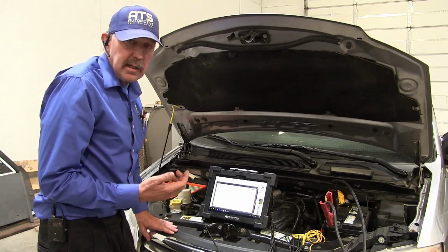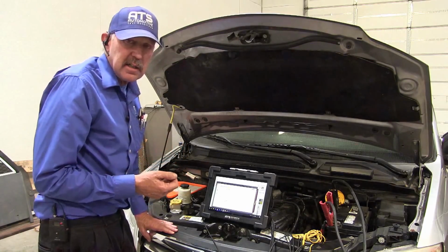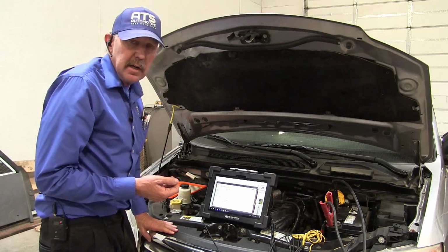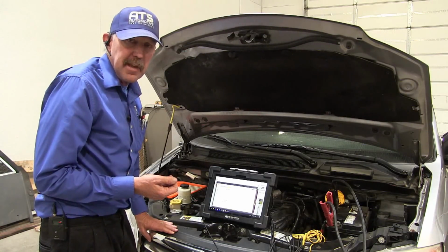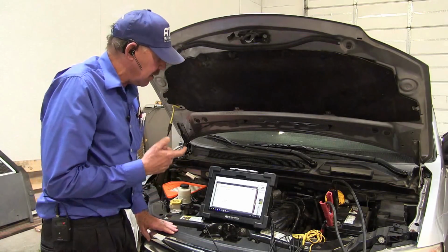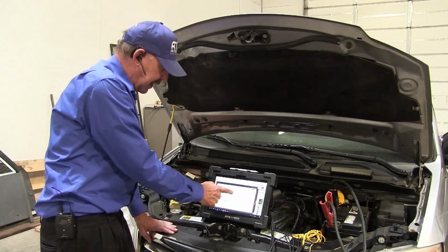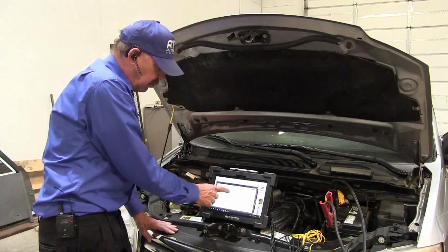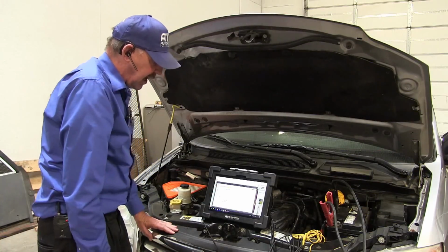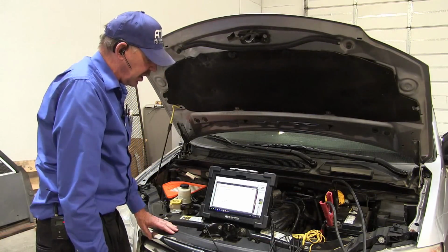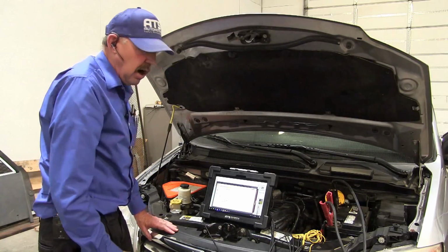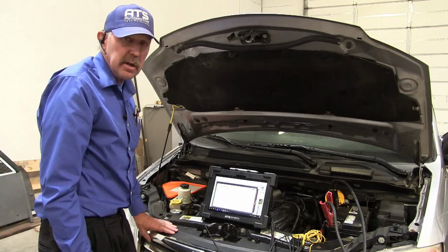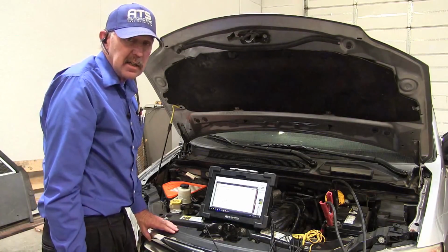So let me go ahead and get into cylinder 1 and let's get a compression reading on 1 to see if we can figure out if that cam is out, because I think that the cam in this bank is out, and that's why I have no vacuum, and that's why they're all missing. And then we have something further wrong with 5, because it's not firing at all. He's sick, and we know we had 1 low cylinder, so we'll still need to run a test on that as well.